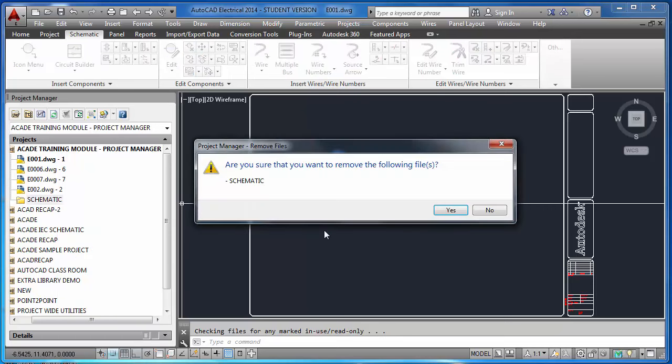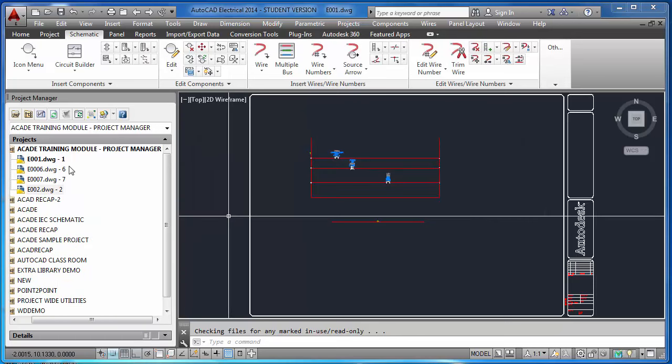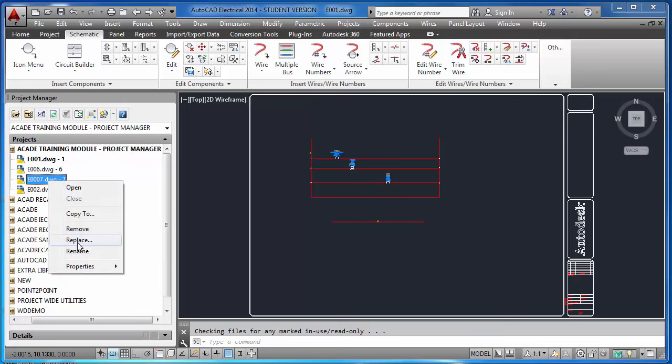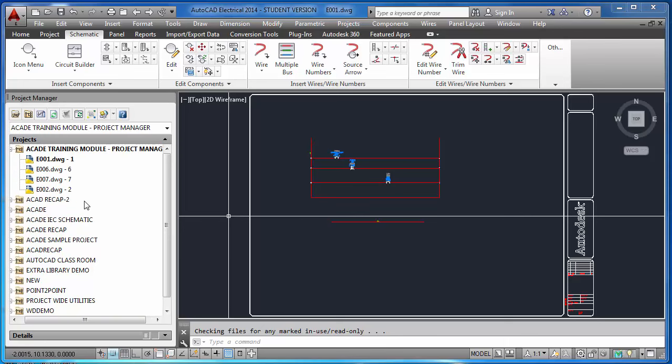Okay. This is just for your better understanding. Now I do a refresh. Now you see, it is coming like E001, that is my file name, and 1 is my sheet value. And in the same way, I will just rename this, reduce 10. Rename, reduce 10. Make a refresh. See, now this is my file name and this is my sheet value. It appears here.